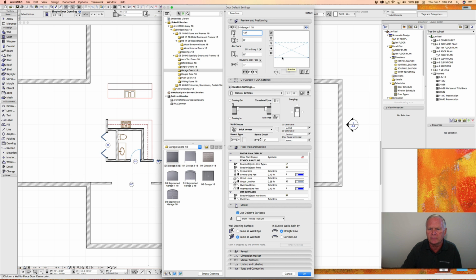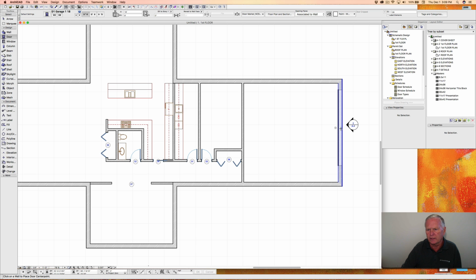That's what it's going to look like in plan. We'll change that 2D level to detailed. Gives us a little more detail for the door. And we're ready to put that door into place. Over there, we'll click on this. We'll find the center point. Now, since we are on an exterior wall, it doesn't matter where that little sunshine is. So we want to make sure that we're on the outside edge of the wall. And then we click there, and this is going to give us the door in place, in center, and kind of shows what kind of space it'll take up when it's in the up position.